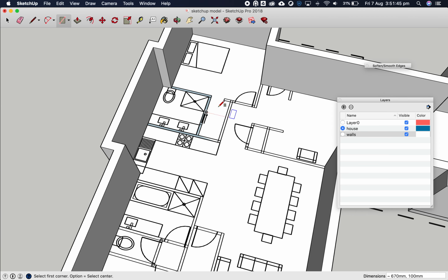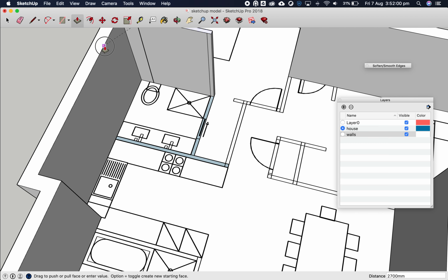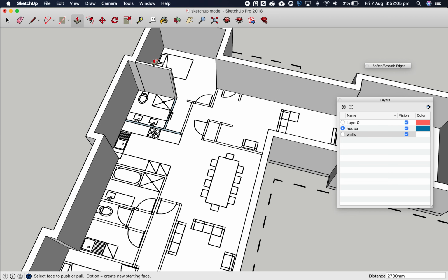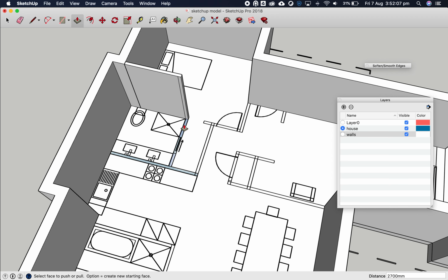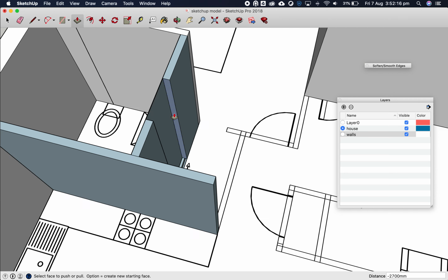Now that that is done, we can do some really cool stuff. Imagine we did the whole thing, and now you can click on the push-pull tool, hover over that wall that's not there yet, click and drag up, and as you're dragging up, move your mouse to the top of this external wall. And lo and behold, you have created your internal wall. Let's do the same thing for this one, and let's do the same thing for this one too. So it's really taking shape now.